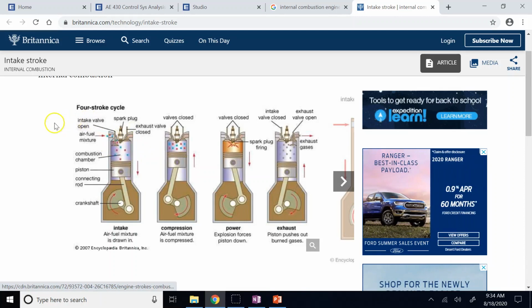What does it mean? It means the amount of suction on the fuel will be bigger, right? So you have a bigger vacuum, it sucks in more fuel, and when more fuel comes in, what happens? Yes, the explosion will be more powerful. The energy that is released and the amount of push on the piston and the amount of RPM accordingly on the crankshaft will be even faster.